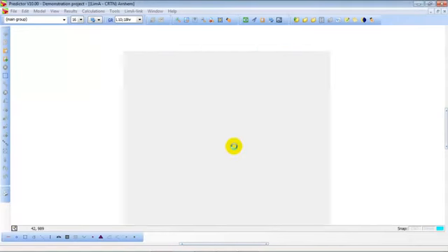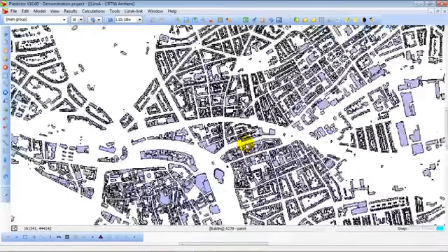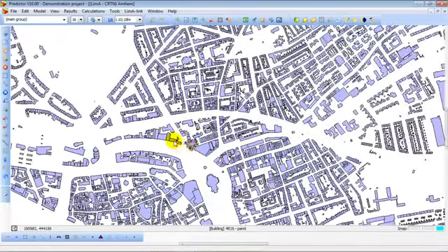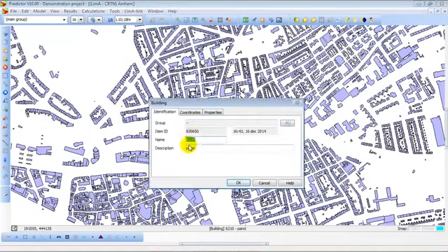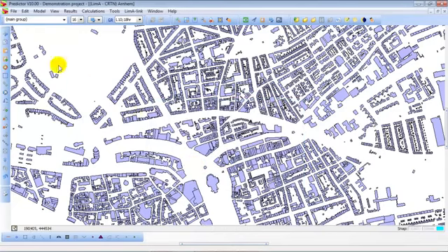So now automatically the shapefile is converted into building items in the Predictor model. In this case around 70,000 building items. All building items are polygons, closed polygons, with a height, with a reflection factor, etc. This polygon has 12.4 meters height attached to it.